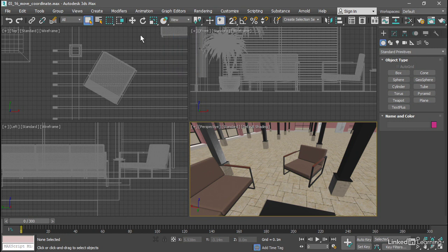The reference coordinate system is sticky for each one of the three transform tools of move, rotate, and scale. So for example, if you choose a reference coordinate system for the move tool, by default that will not affect the coordinate system for rotate. They're independent of one another unless you change that behavior in the preferences. The default coordinate system is view.